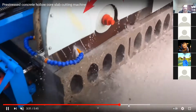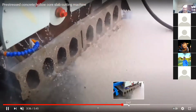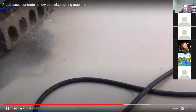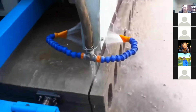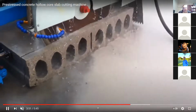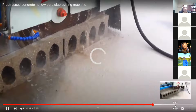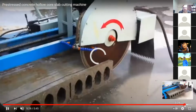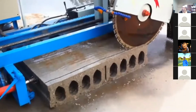You don't really need any rebars on the top because it's not needed. It's going to be much cheaper when you just do it this way. So you don't want to add complexity to it. You don't want to add top steel and then hold it in place and put some chairs. This is going to be expensive in this case. You'd like to go as simple as possible because this is going to be mass production, so you cannot afford to put compression reinforcing. You just add more tension at the bottom. That's what you do.